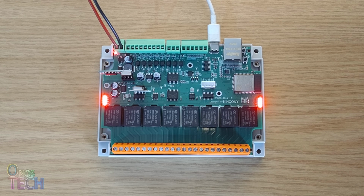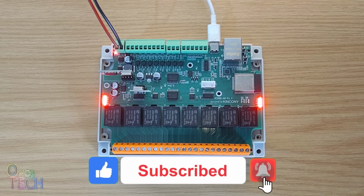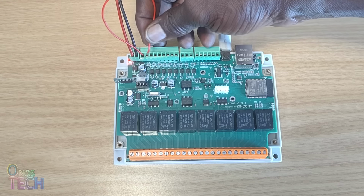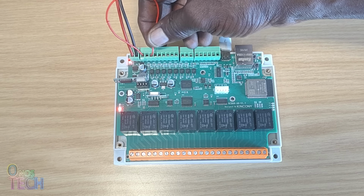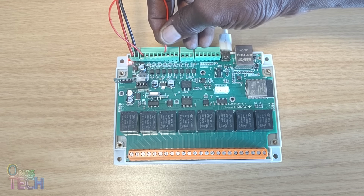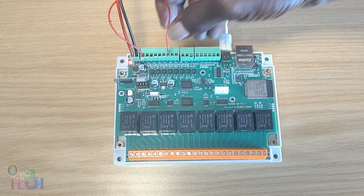You've got your Kincony board running OpenPLC, but there's a problem. The inputs are not working yet because they are behind a PCF8574 expander. OpenPLC is blind to them until now. Today, I am showing you the C++ fix to unlock all 8 inputs, in addition to the 8 outputs from the last video, and build your first real industrial logic.